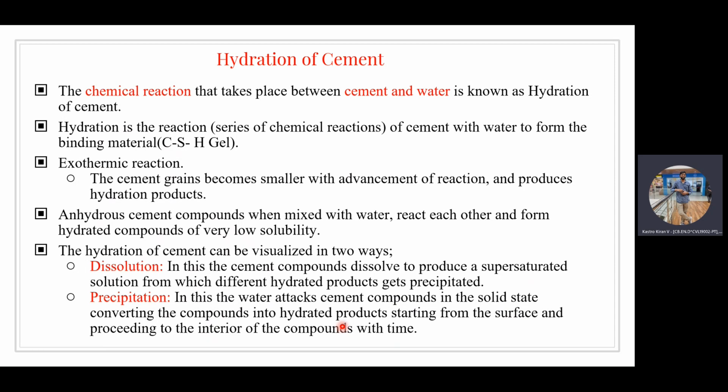This is, in general, the hydration of cement. If you have to keep it simple, the definition of hydration of cement is a chemical reaction that takes place between cement and water. And remember, it's an exothermic reaction. This is the most important one. Exothermic means it liberates a certain amount of heat into the atmosphere whenever cement comes in contact with the water.